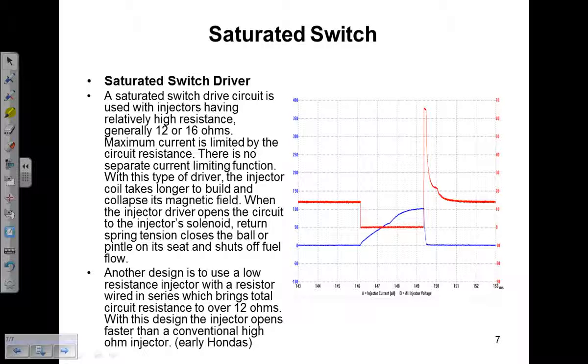Also, of course, injector current and voltage waveforms. We're going to review what we just talked about. And I have a whole bunch of case studies: shorted injectors, stuck injectors, voltage waveforms, current waveforms that aren't right, to emphasize what we look for when we do fuel injector current ramping and voltage waveform testing. Section 18 coming up next.